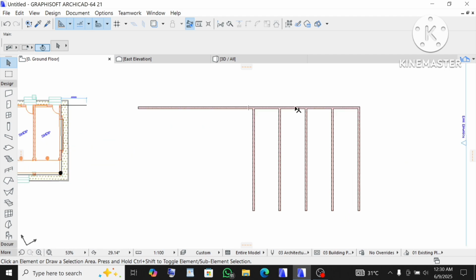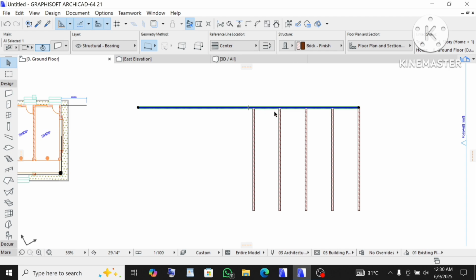Now we'll click on this wall. Make sure it's on this arrow tool. Click on the wall and remember that the shortcut for offsetting is Ctrl Shift D. Hold Ctrl, hold Shift, and hold D on your keyboard, then leave it. So click, take it down, all right, now type the distance 6225, wall inclusive, 6225, press Enter.